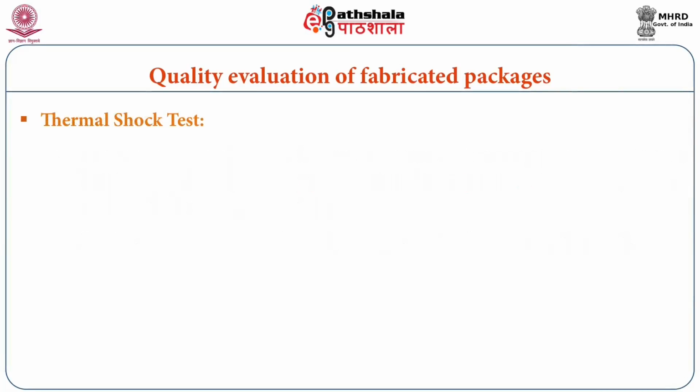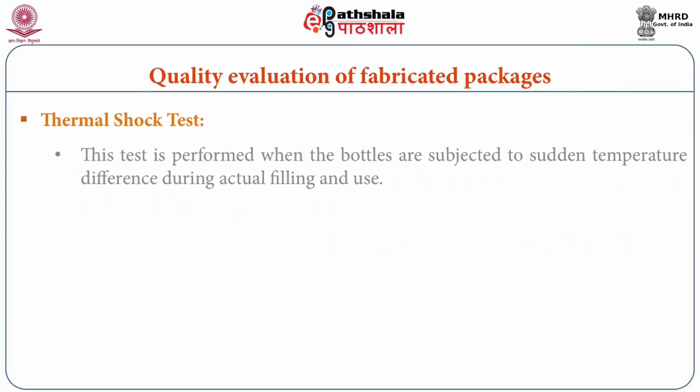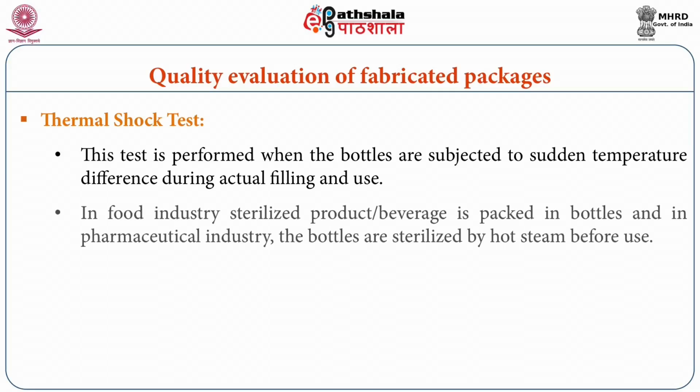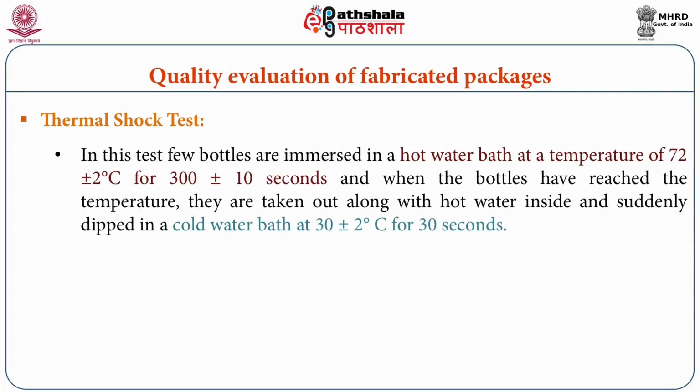The next test for bottles is the thermal shock test. This test is performed because the bottles are subjected to sudden temperature difference during actual filling and use. In the food industry, sterilized product or beverages are packed in bottles, and in the pharmaceutical industry, the bottles are sterilized by hot steam before use. In this test, a few bottles are immersed in a hot water bath at a temperature of 72 plus or minus 2 degrees centigrade